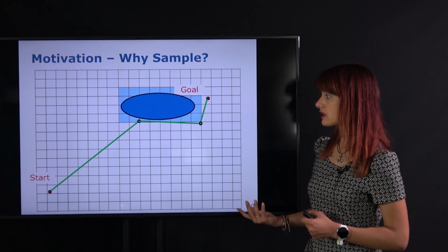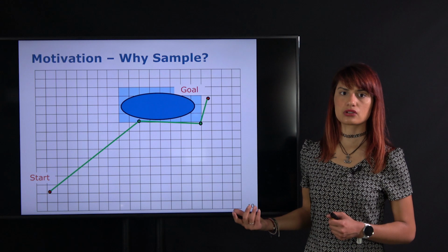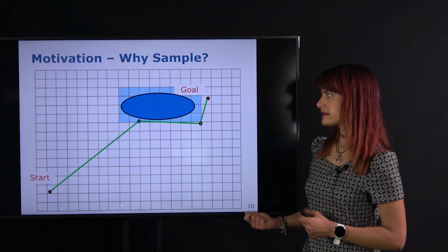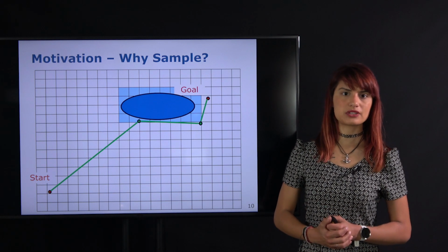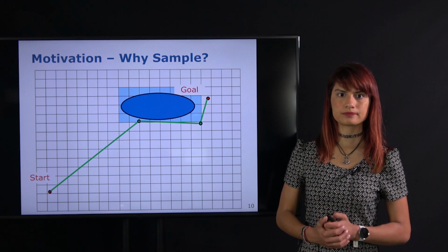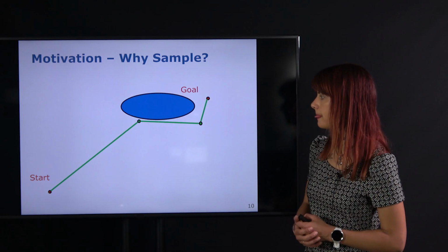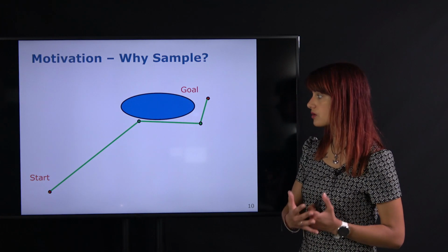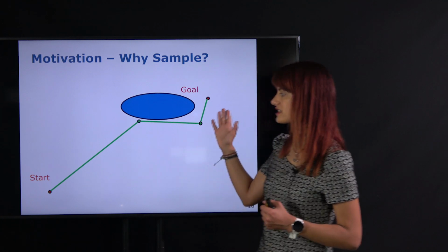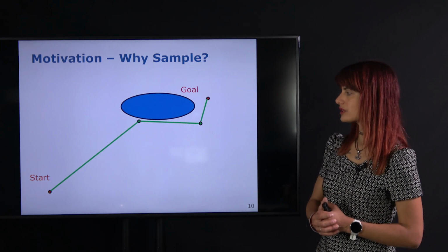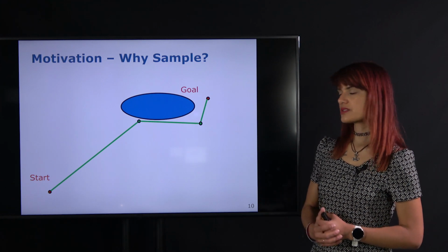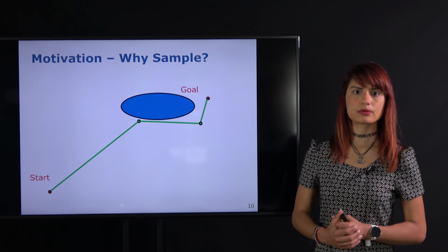And this is exactly the key idea that's underlying sampling-based approaches and the main insight that they use to obtain computational efficiency. So in this case, we don't need the grid at all, because we can just operate based on the nodes that we have sampled and connect them together to form a collision-free path, which corresponds to our solution of the path planning problem.